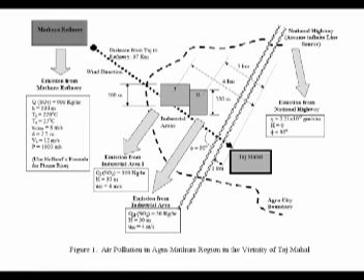There is another source which is also 500 meters in size. Okay. And this is located at some 4 kilometers, and this is located at 3 kilometers. And what you see here is a national highway which is going like this. Okay. And details of the national highway, the emission rate is 2.21 times 10 to the power minus 2 grams per second per meter, as you remember the units that will be.